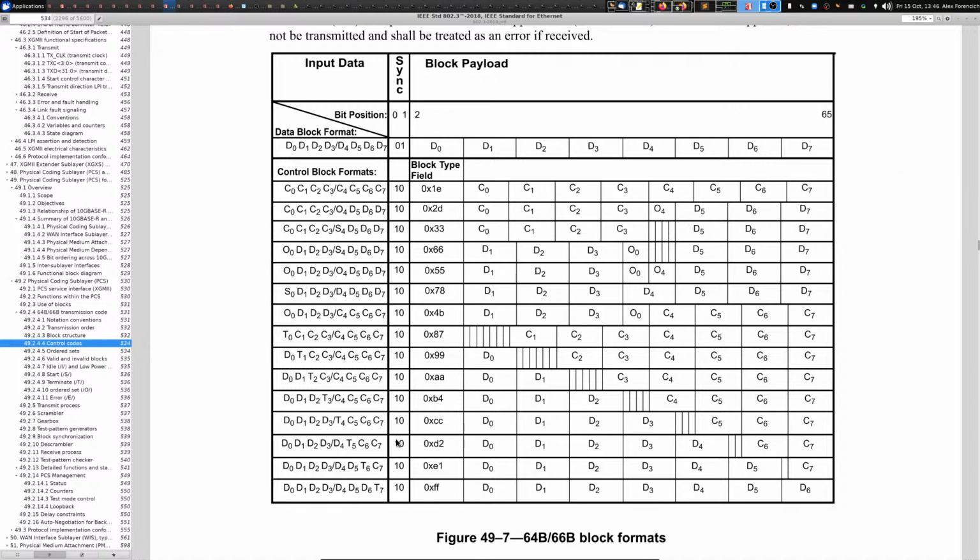And there's a couple different techniques that are used to do that, right? The first one is we take advantage of the fact that the encoding for XGMII is relatively fixed, right? There's two places you can put a start control character, and those are the only two places, right? Well, because we're pulling in 2 cycles, then there's 2 possible positions, because in each cycle there's only 1 possible position.